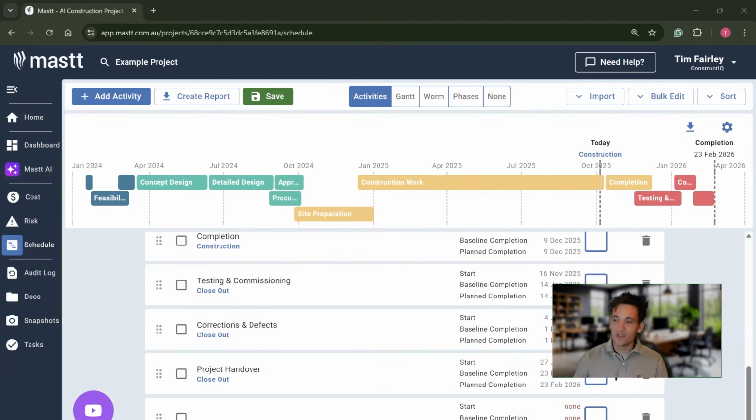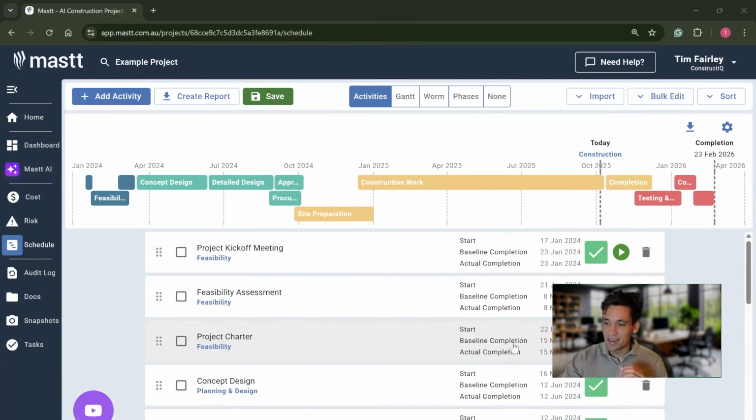So the big milestone, in any construction project, is going to be the completion date. As a construction contractor, this is the date in your contract, and it's the date the liquidated damages kick in. So it's an incredibly important date. You might have several portions, where you have multiple different finish dates because different scope needs to be completed. Those can be displayed. You also typically display the project initiation date and the access to site date. So those are the key dates in any construction project that should be displayed on the schedule.